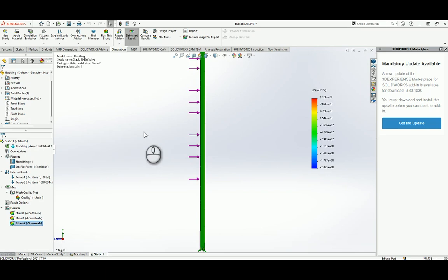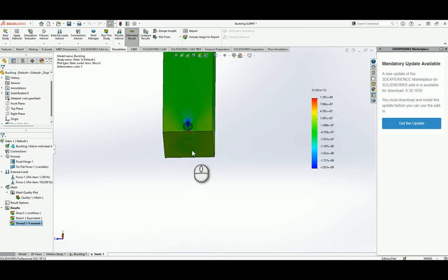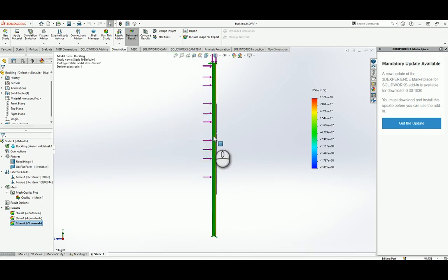We talk about automatic shift. So this is our stress. You notice the entire thing is green, meaning that it is more or less around the same value throughout the beam. We have these peaks here again because of the non-ideal situation where we have the hinge. So we'll be interested in the maximum stress, which we predict is at the center.